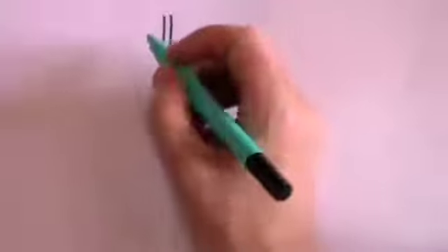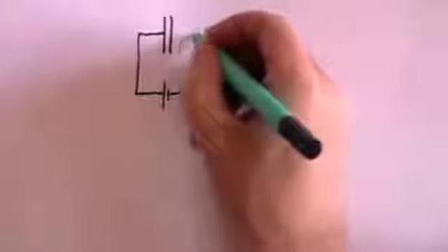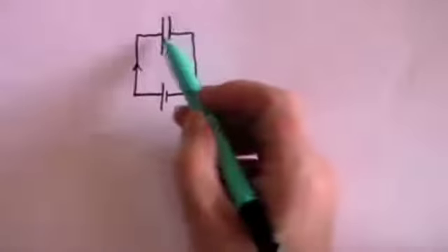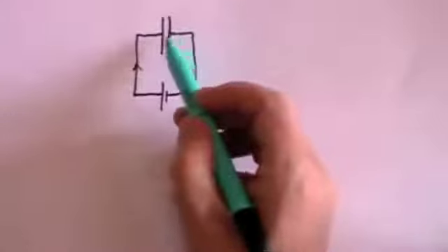Let's first think about a capacitor. A capacitor is really just two metal plates opposite one another with a small gap between them. If we think of it firstly in DC terms, so we're going to put it across a battery, then what happens? The important thing is that although a current flows, at least initially, no current ever flows between the two plates.